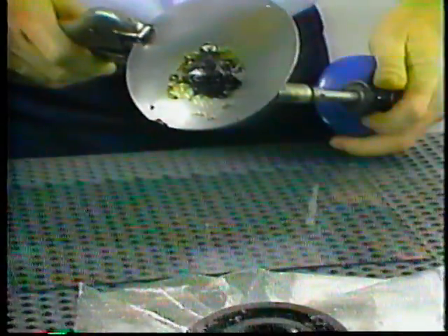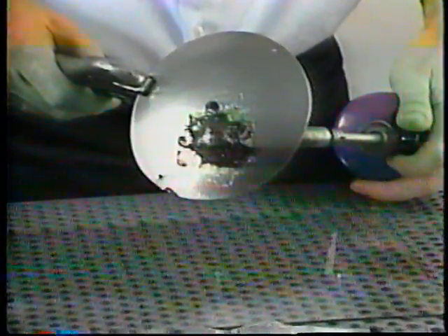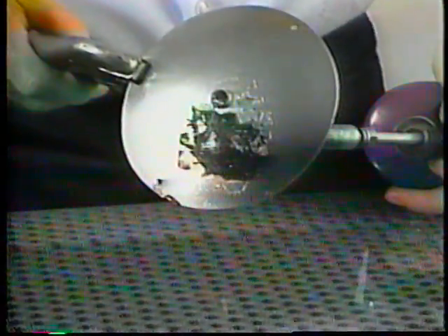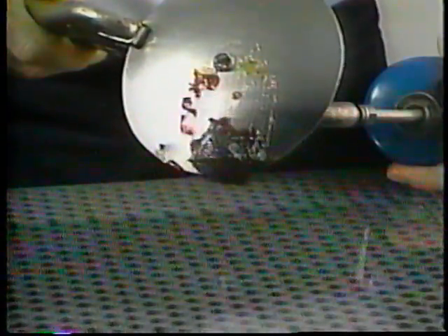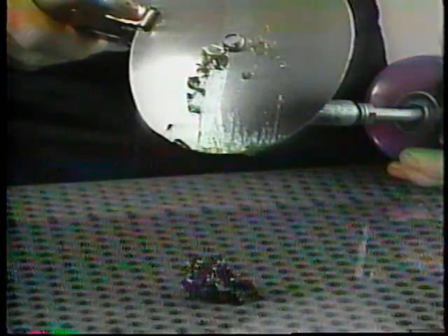At high temperatures, the oil in the grease thins out. When temperatures are high enough, at a temperature called the drop point, the thickener itself will usually melt. Once grease is melted, it may not return to its original consistency, even after it cools.